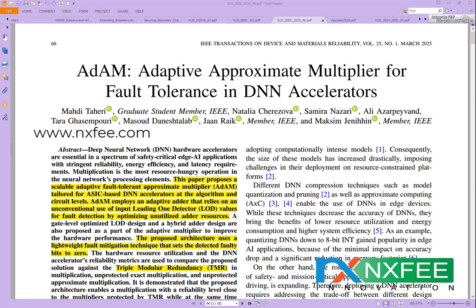Here the truncated and higher order bits are variable parameters, which enable flexible precision control and more accurate error management across various applications. A compact Brent-Kung adder is also used for logarithmic value additions, while the anti-logarithmic unit reconstructs results adaptively with a log n shifting for accuracy and efficiency. The novelty of this design lies in integrating hybrid parallel prefix adders with a variable truncated and higher order shifting method, making it more reliable and versatile than existing approximate approaches such as the adaptive fault tolerant approximate multiplier.